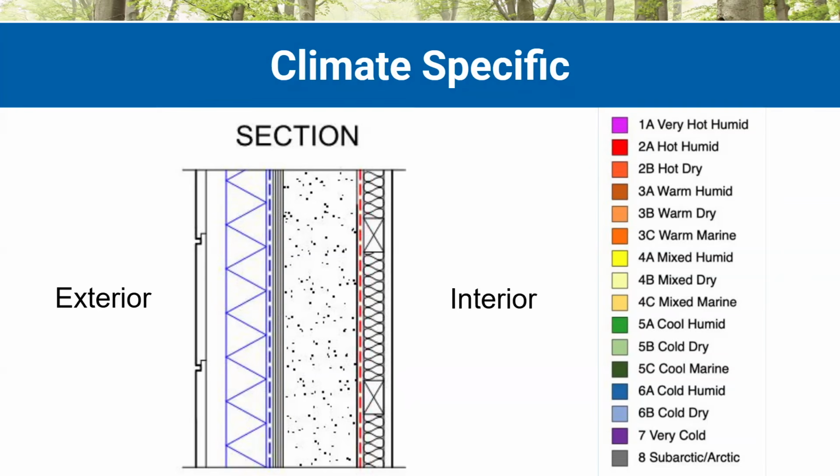For dry, for B, that exterior, it's very helpful for it to be airtight, but I really want to be prioritizing that interior air barrier. Our sheathing can be getting quite cold during those winters, and I want to keep my warm air off of that sheathing surface. So now we're maybe switching to 2 inches of exterior insulation.